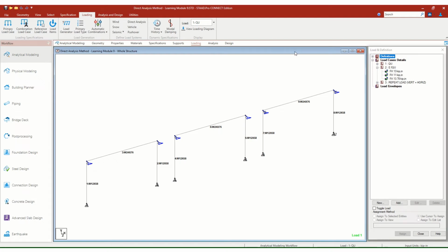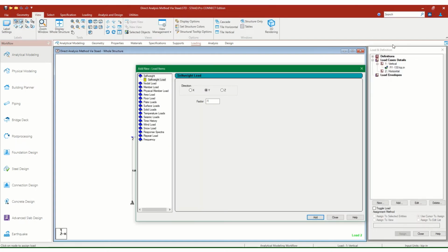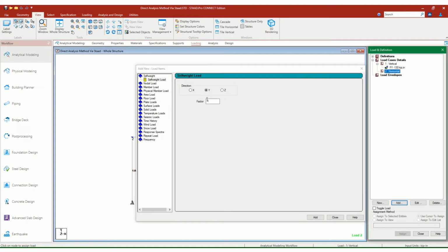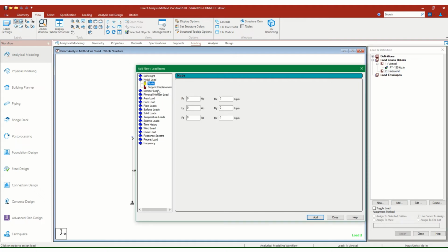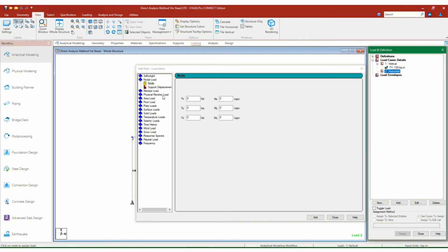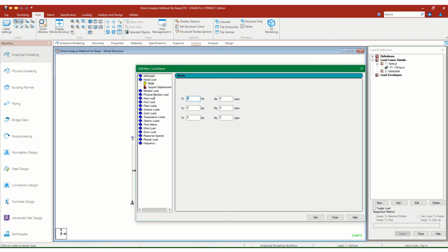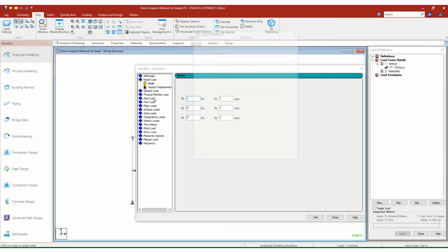So I'm not modeling the structure in this displaced condition, if you will, the tolerance that's allowed via erection. So I'm not modeling the erection imperfections. I'm just going to add additional vertical lateral load in order to capture that. So come back over here, 13.78. Let's define that nodal load in the horizontal. We're under that. It's a lateral load, positive x direction, 13.78.